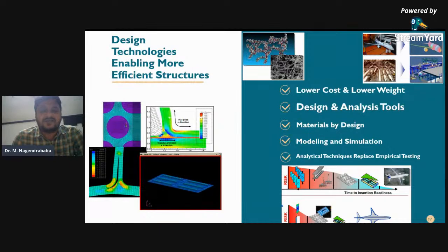A variation of this trend exists in metallic structures, as more components are conditioned in forgings to get the near net shape, reducing the amount of machining. Elephant skins, roughened shapes, and thin floor sections all reduce materials cost and the total number of components, but setup and fixturing continue to be challenges. Designers, machinists, engineers, and machine tool and cutting tool partners are developing new solutions to keep the evolution churning forward.